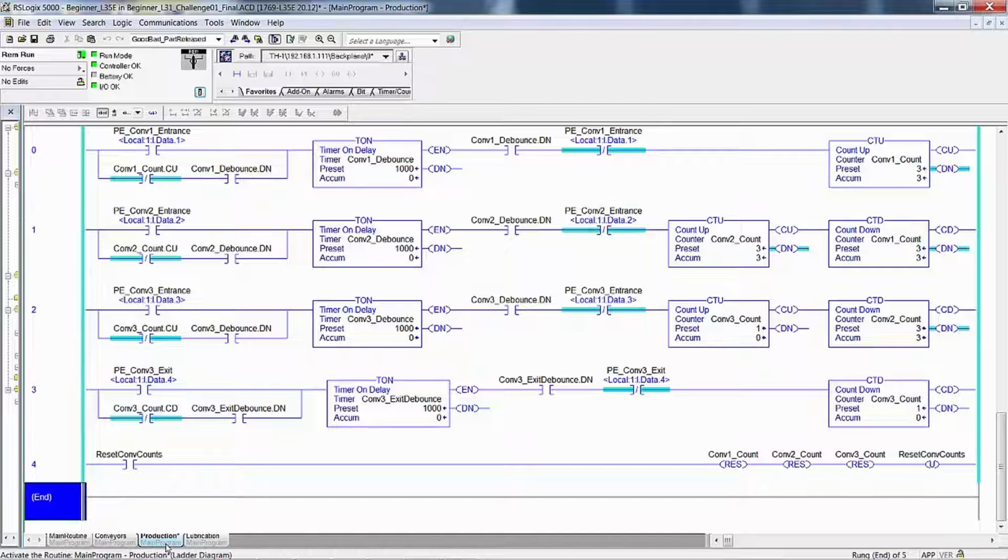Once that is reached, conveyor 3 does not run unless the manufacturing area is calling for parts or a carton downstream. To pass a carton onto conveyor 1, we need to transfer a carton onto conveyor 2 and transfer a carton onto conveyor 3. For this to function correctly, the controller should see PE1 on, PE2 on, PE3 on to simulate the train of cartons moving across the 3 conveyors.